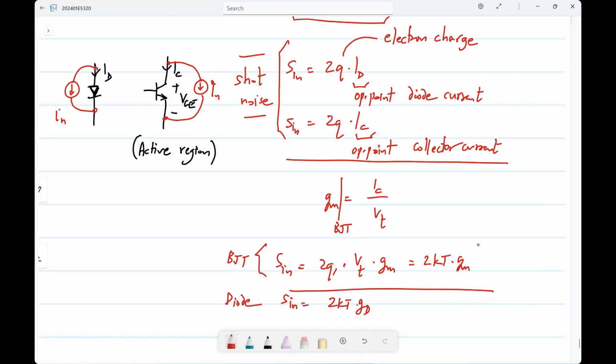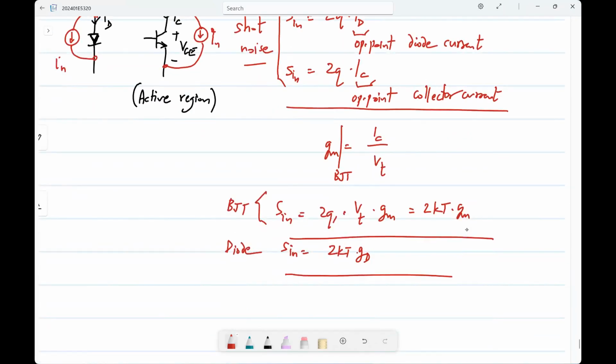Just as thermal noise is fundamental to resistors and MOS transistors, shot noise is fundamental to bipolar transistors and diodes, because the very mechanism of current in a bipolar transistor is this firing of electrons from the emitter to the collector, and that rate is random, so you will always get this. There are other types of noise which are a little less fundamental, nonetheless important. We'll get to that, but this is very important.